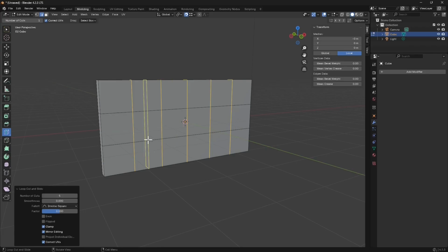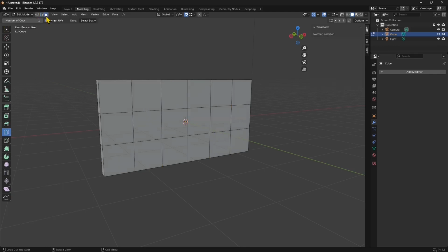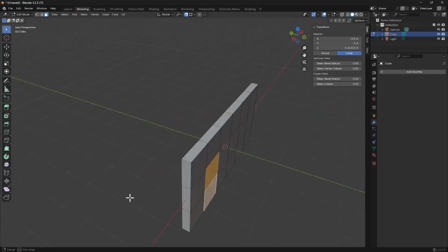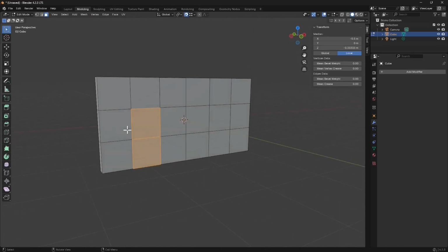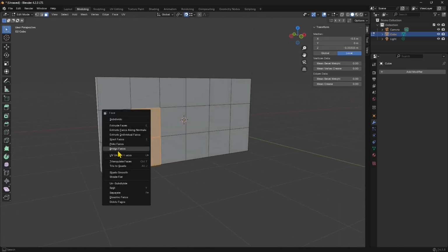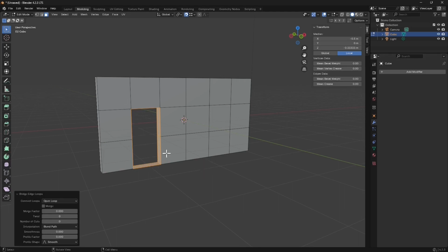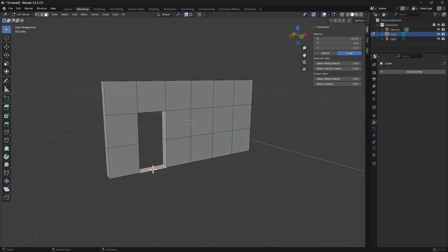Okay, so once you have finished cutting here and there the wall, we can also start to create the holes that will host the windows and the doors. So I will select the move or the select tool, otherwise I will keep on cutting, which I don't really want to do. Make sure you are not in the loop cut anymore, and select by holding Shift. You can select multiple faces, so you want to select from both sides and then right click and do Bridge. So that's the command, the magic command, which will create a hole using those faces. Instead of using the Boolean, which is less precise, you can do it quickly using the bridge.